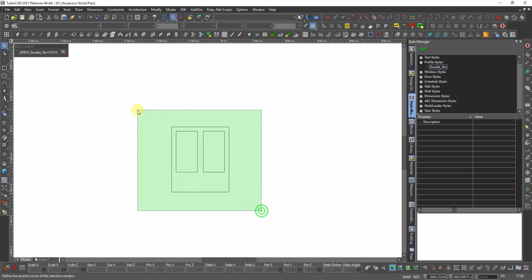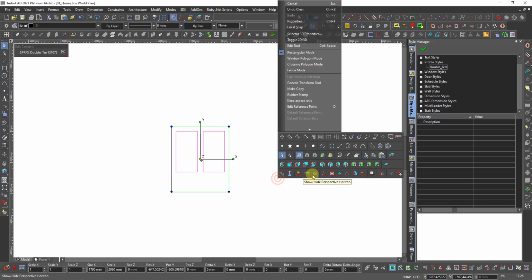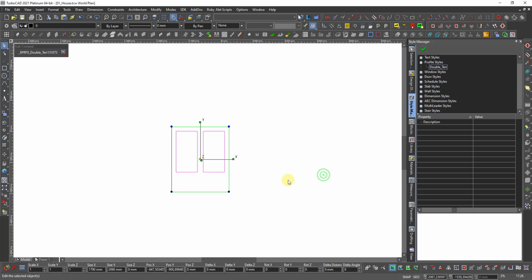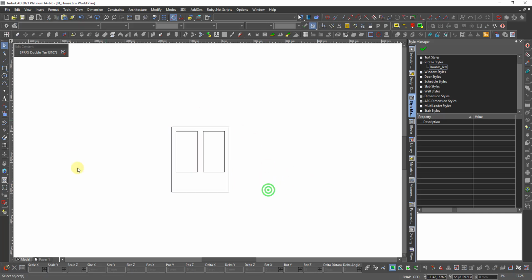So then I select them, I say plane by world and Alt Shift W. Else you will get this warning, this may be moved a fraction of a millimeter, and then it's not the same work plane, blah blah blah, it doesn't work.